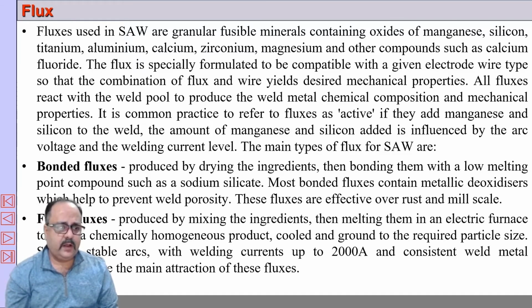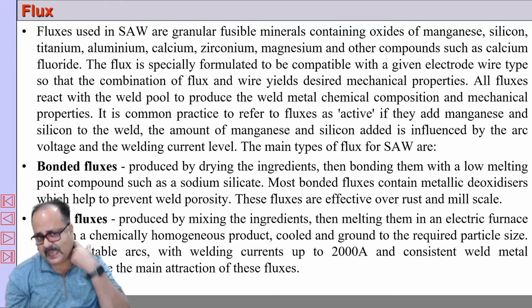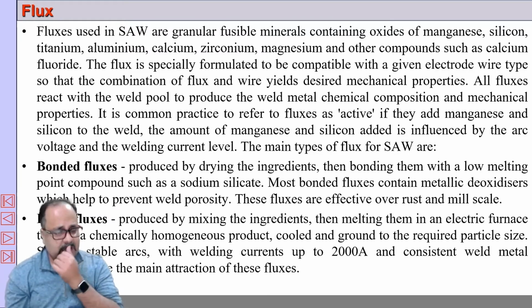Whereas fused fluxes are basically heated. The flux mixture is heated to a high temperature and forms a fused mass which is broken to the required size and then can be used. However, it has certain limitations, like you cannot add the deoxidizers at high temperature, so that is an issue with fused fluxes.